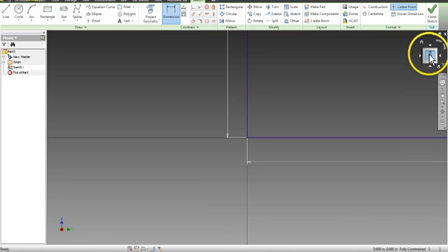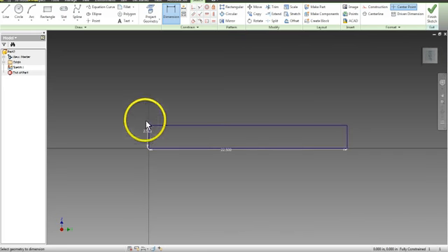I'm going to click on where it says right over here. It'll zoom us out, so now I've got a rectangle that's 2.5 tall and 22.5 long. Now I need to get to the 3D world. The 3D world is where I can give this some depth. Right now it's just a two-dimensional figure. It's got a horizontal dimension and a vertical dimension. I want to give it some depth. So I'm going to click the green check mark in the upper right-hand corner of the screen.